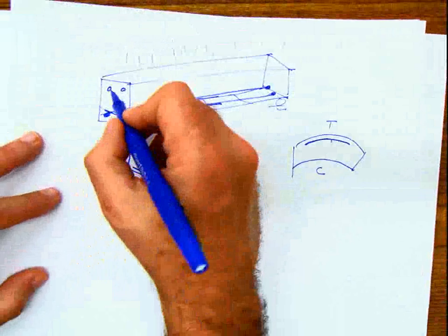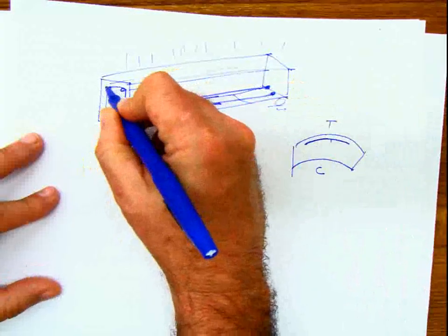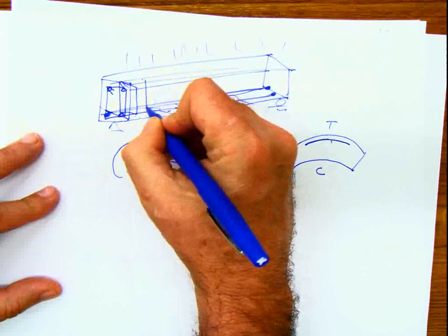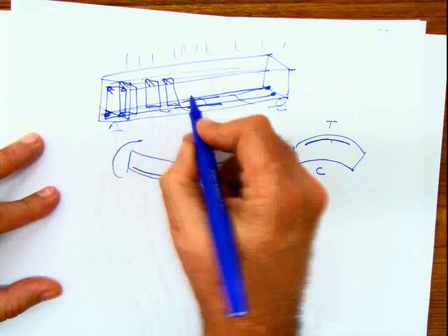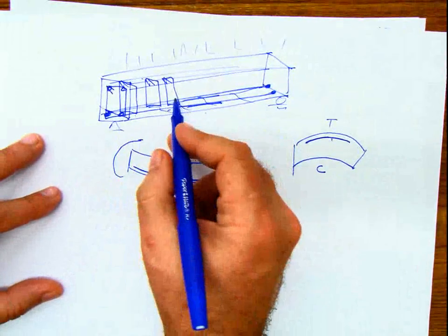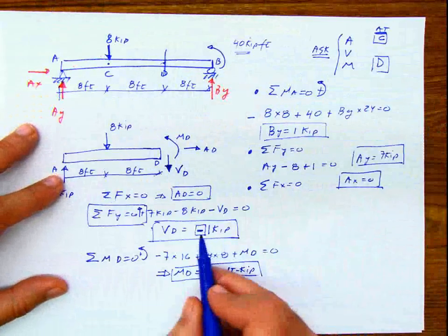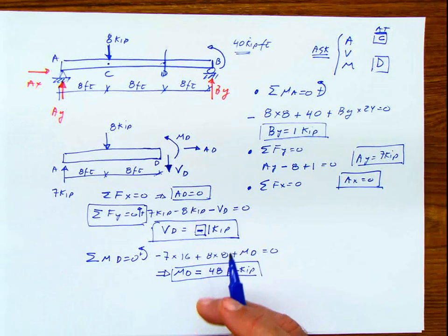Now I'm pretty sure that you have also seen that whenever you have a concrete beam like that, you also have some structures that come like this, bracing all the rebars together. Those are called stirrups. Those stirrups are calculated with this value, with the shear. And of course you will see that later. Also the thickness of the structure is calculated with the stirrups.